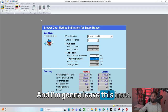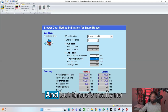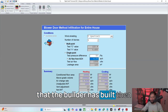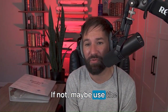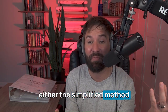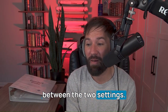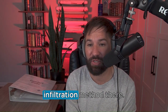I'm going to leave this here. I'm pretty comfortable with that because I've done enough work with them in the past. But there's really no replacement for data. If you don't have blower door information from prior houses that the builder has built, then that could become a little bit of an issue for you. If not, maybe use the simplified method, but those are the 2 methods to choose from, either the simplified method or the blower door method. So take your pick, however you want to use it. I showed you how to toggle between the 2 settings. You just go to setup and then options and then choose your infiltration method there.